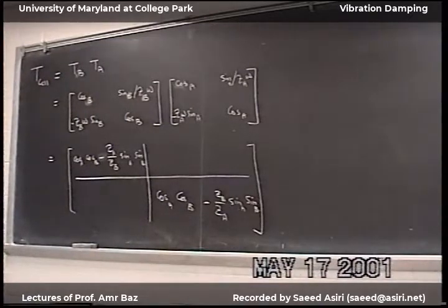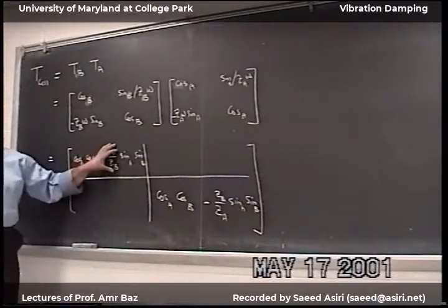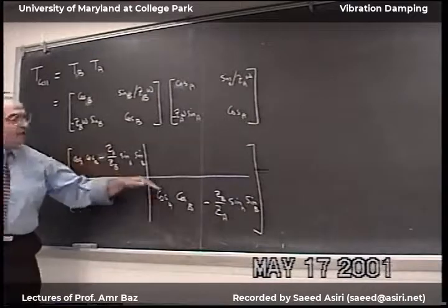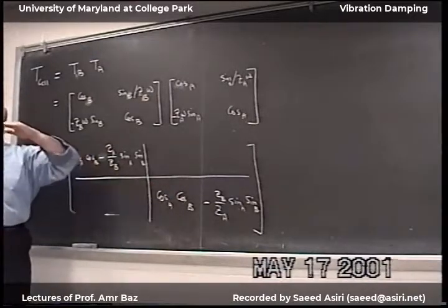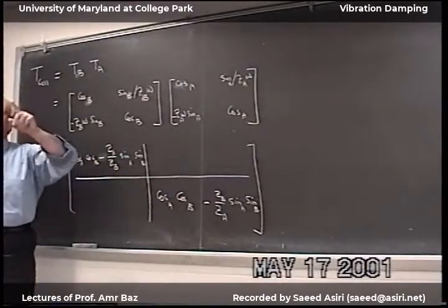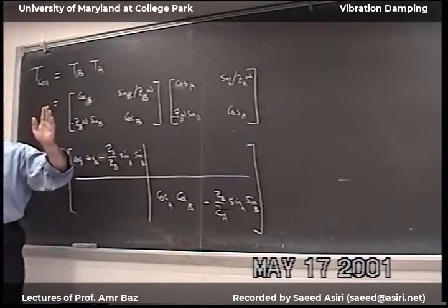Okay, so from all this, if we have a periodic rod, all that I have to worry about is the impedance difference between these two items. If this impedance ratio is 1, then this will have eigenvalues whose absolute value is equal to 1, and everything will propagate.